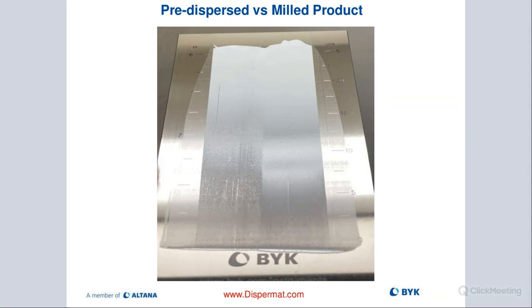So here's a good example. We ran a product, and on the left side, we show you a pre-dispersed product. So we would just use a Cowles blade. And on the right side, we show you a fully milled product. That was actually done with the basket mill. And you can see on a Hegman how different they look.